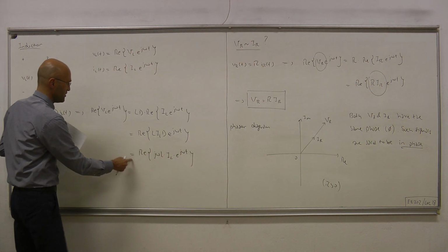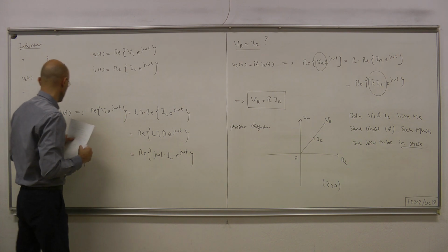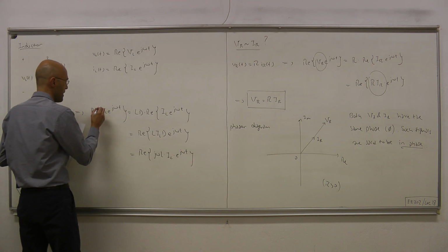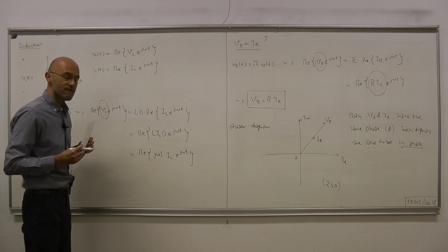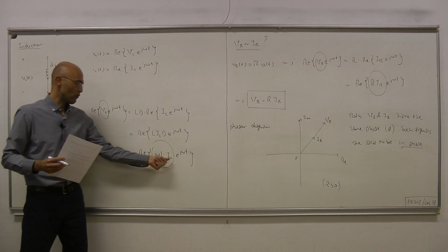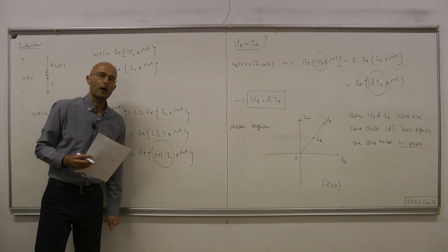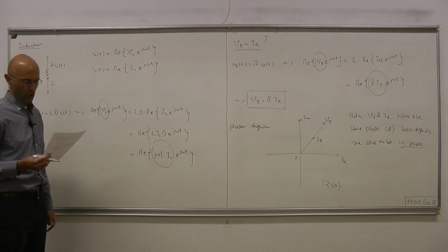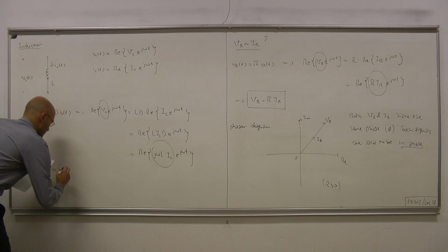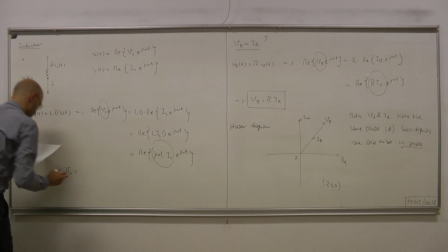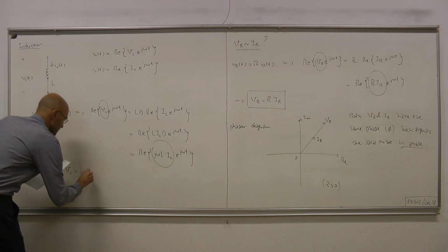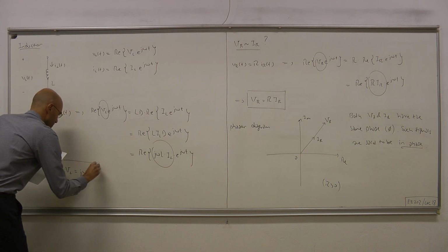Likewise, this equality holds for all times, which it does because the terminal equation holds at all times, so it must be that the phasor of voltage must equal the phasor of current that's being multiplied by that complex number j omega L. So let's write our finding here: VL equals j omega L times IL.